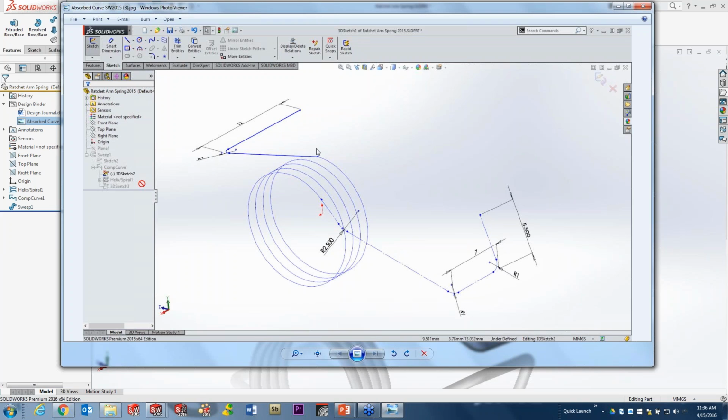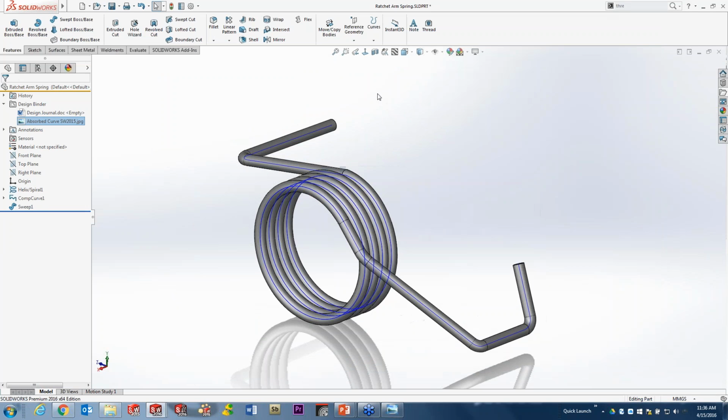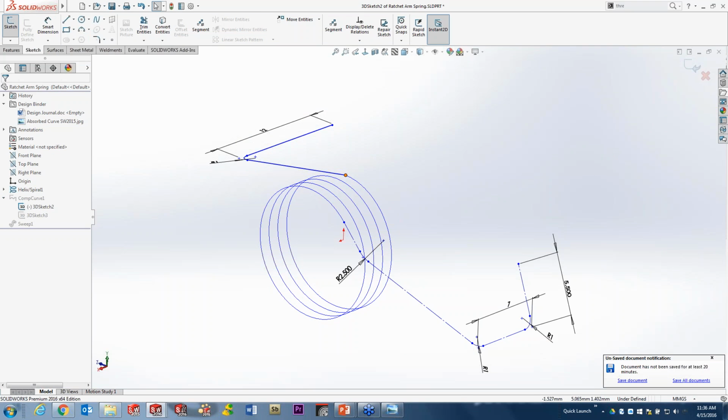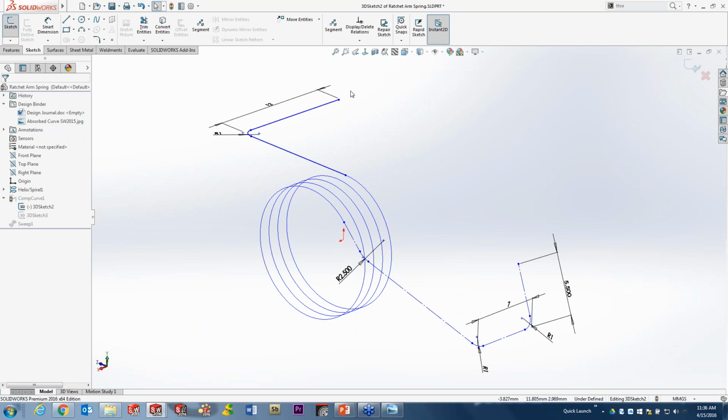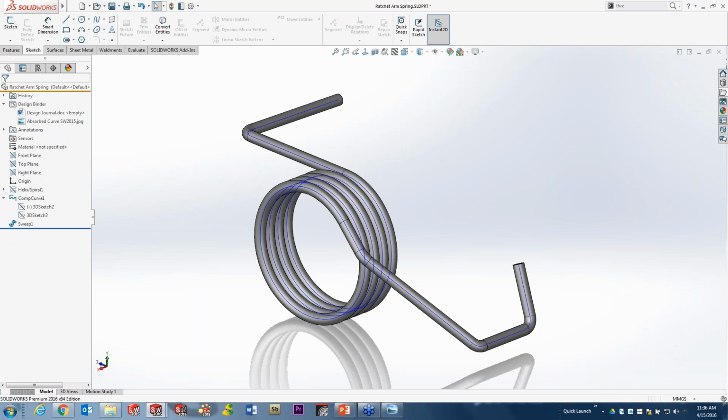And in our situation here, we've actually got an area where that curve and the 3D sketch don't blend tangent. Well, to edit that in 2015, I would have to delete the entire sweep and then redo it after fixing the sketch entities. But here in 2016, because we're not burying those, I can easily go to the sketch. We can edit the sketch, and if you take a look right here, those two aren't tangent to each other. So just by picking on that endpoint, or in this case grabbing the curve and the line, we can make those tangent, which will update the location here. Now we didn't need to define a circular profile, so nicely enough, it just has a circular diameter as its driving value, therefore it updates flawlessly.